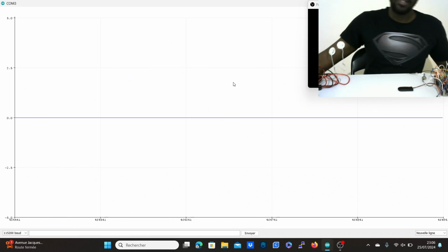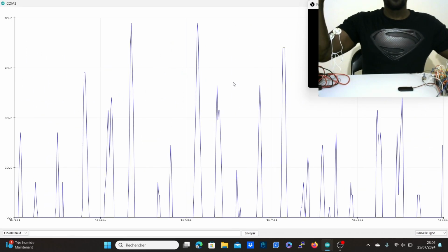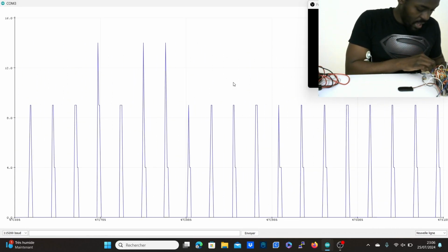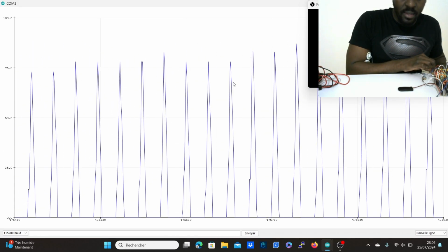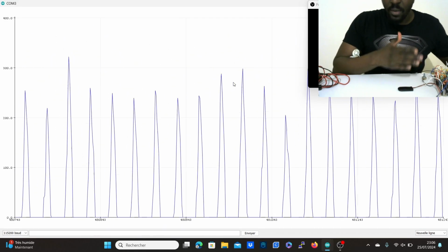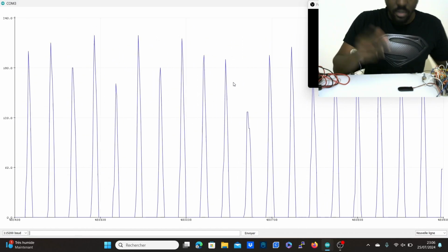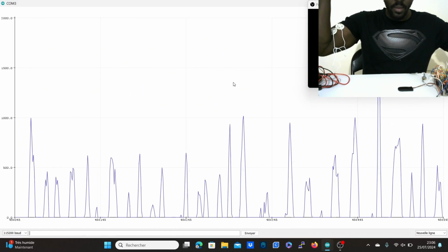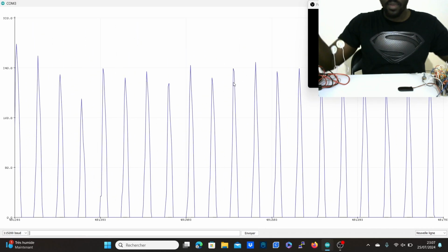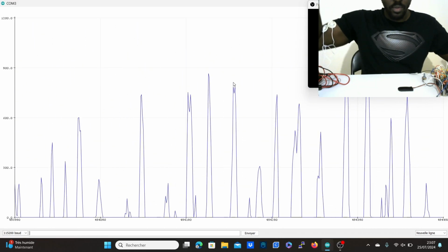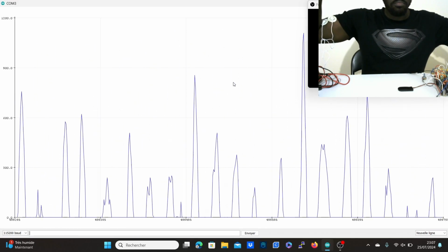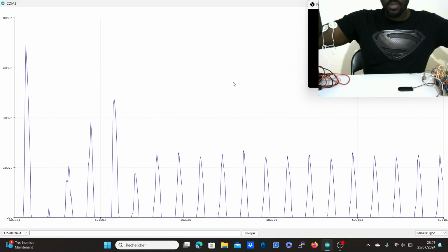And if I put it away, it's like my system is just working normally. And if I amplify the gain, here I'm at maximum, just like what I did with the notch filter. But here you can see when I'm contracting my muscle, I have a result. I can go up to pretty much 1 volt.